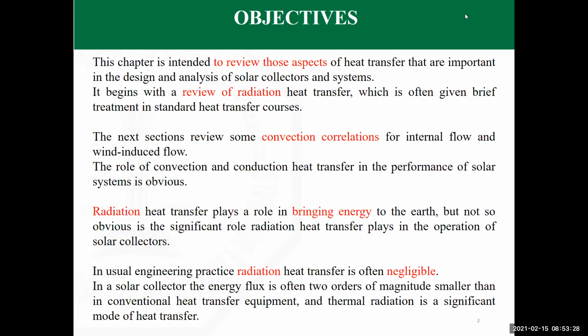You get a feeling from the numbers you deal with in problems, especially problems with multi-mode heat transfer, where you may have a combination of conduction, convection, and radiation, that unless there is combustion or fire, or basically a very high temperature source, radiation can be neglected.